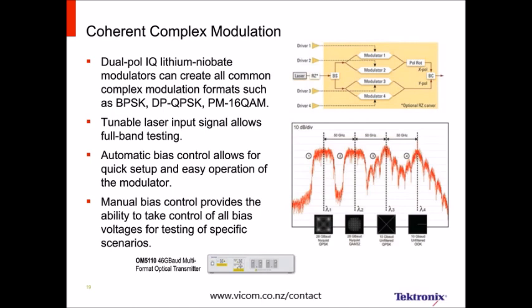Down here is some example of the spectra that you can get out of a lithium niobate modulator. And a lot of this also applies if it's indium phosphide. On the far right is what you get if you do basically on-off, fast rise time switching. You get these multiple lobe sinc functions because of the fast rise time. It's basically the Fourier transform of a square pulse, and so the spectrum ends up being a lot wider than you might expect. This is for a 10 gigabaud signal.